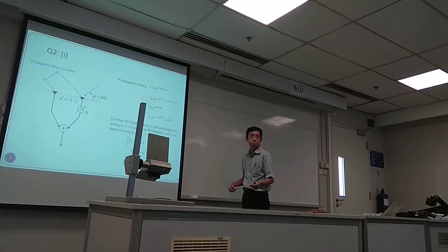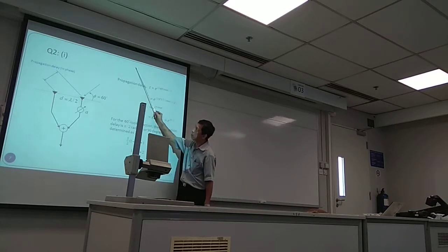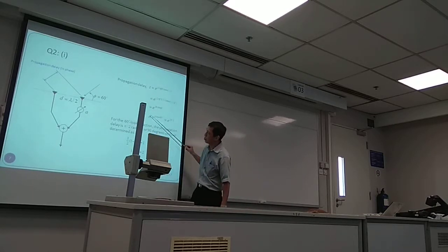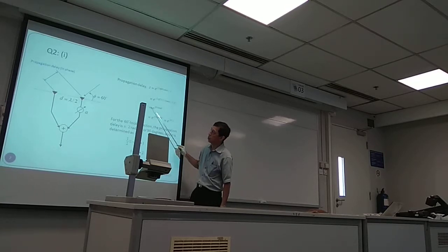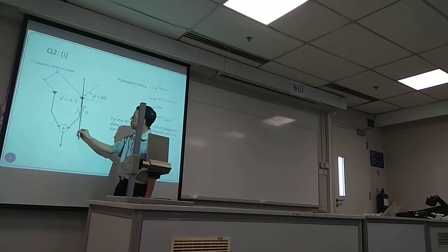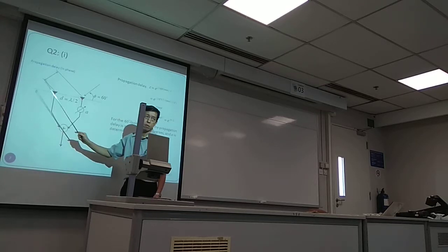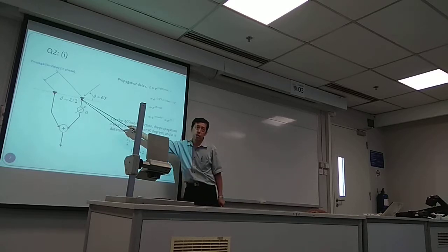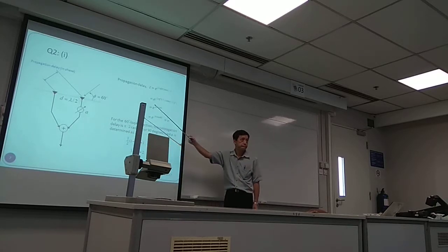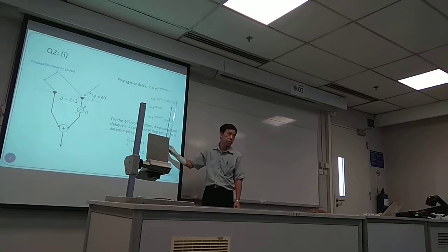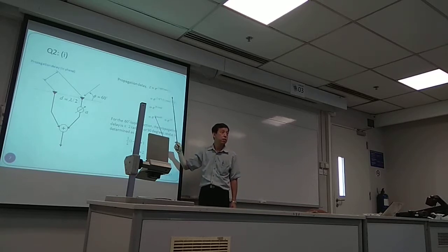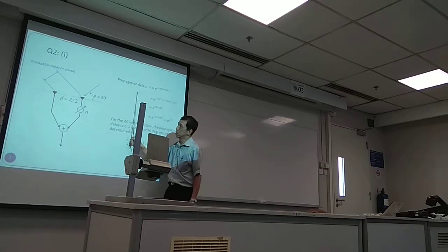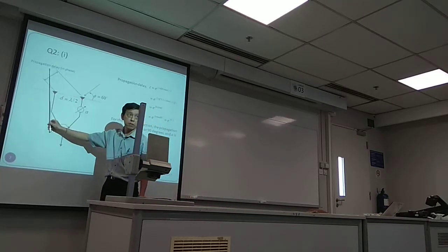Does it make sense? Now, instead of having a signal coming in from 60 degree direction, if you have a signal from the end fire direction, when the wavefront is traveling this way, first you impinge on the element on the right, then subsequently the element on the left. What would be the phase delay if you have half wavelength? Yes, 180 degree, right? Correct. So that would be 180 degree phase shift.